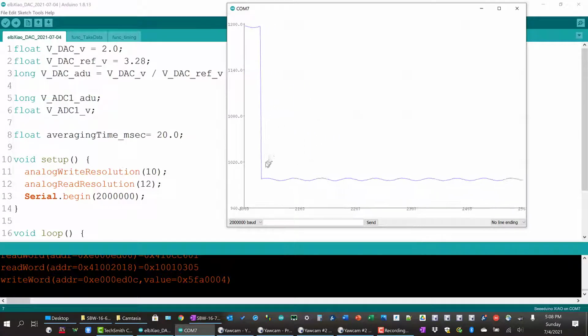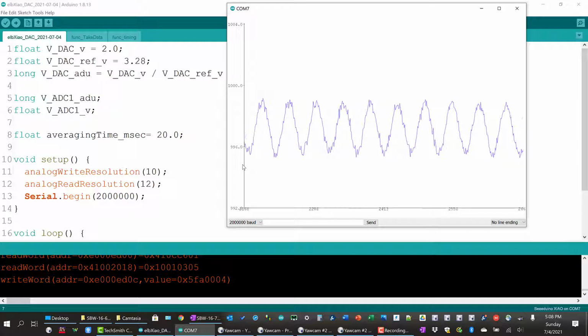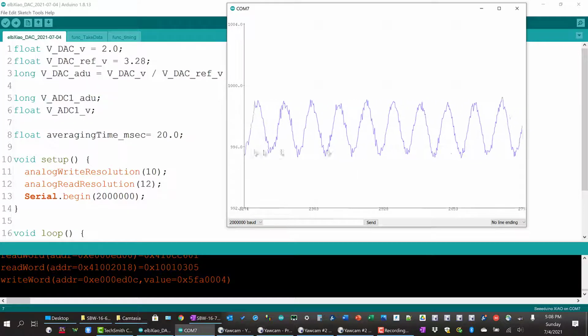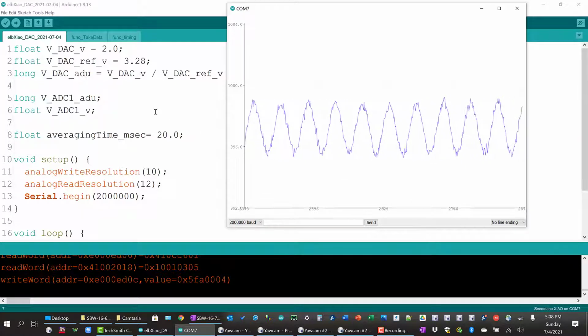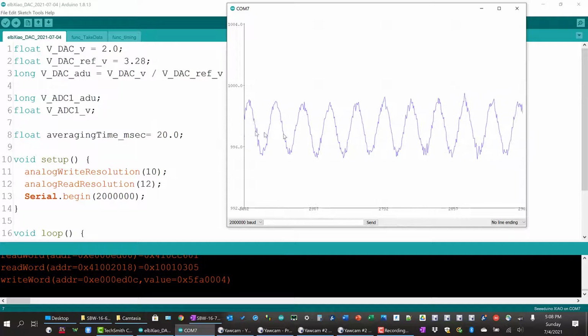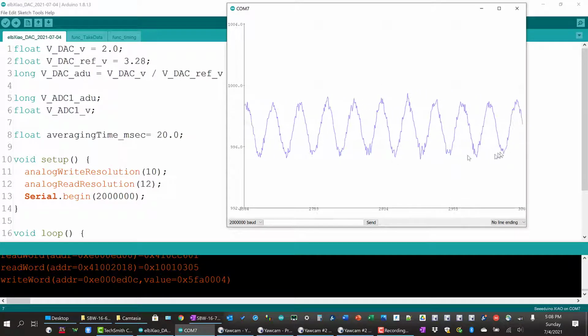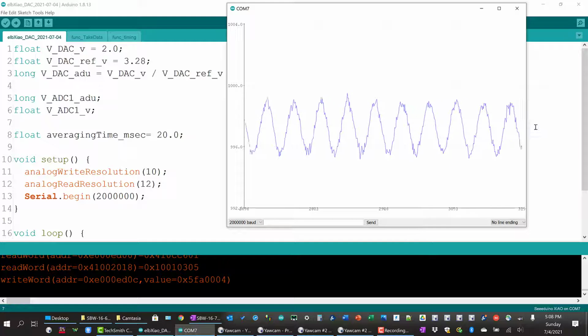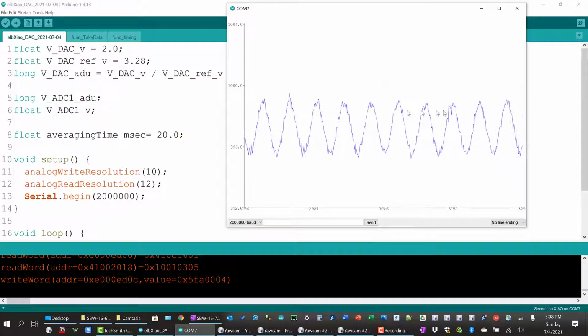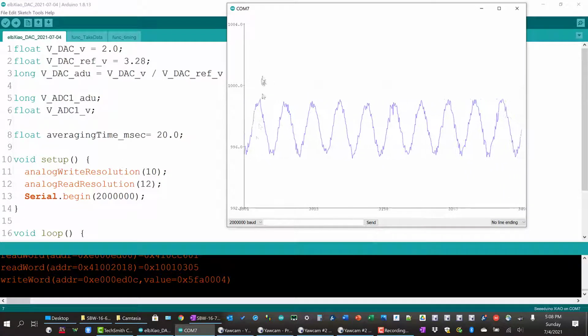So in this first video we've looked at how to change and adjust the time base, and we do that by averaging the data as it's coming in and then displaying the average point, and that controls the total time full scale. In the next video we'll look at how we adjust the vertical scale.